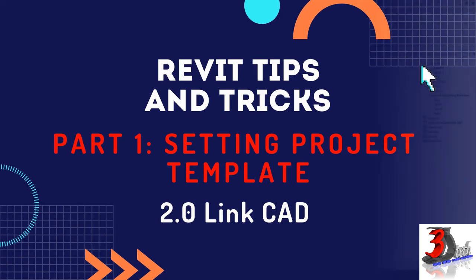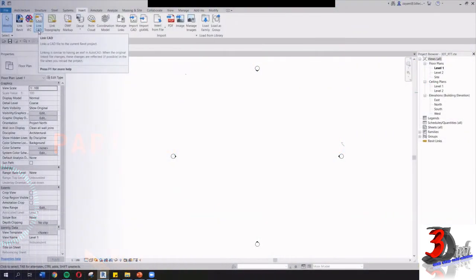So link CAD is basically you bring in the AutoCAD drawing, but the AutoCAD drawing will only be treated as external references. So whenever you want to restart your model, Revit will read the link CAD from the file path that you have specified first. But let's say you change the file path of your AutoCAD drawing. Then Revit will not be able to read the AutoCAD file. So it will always be treated as an external file.